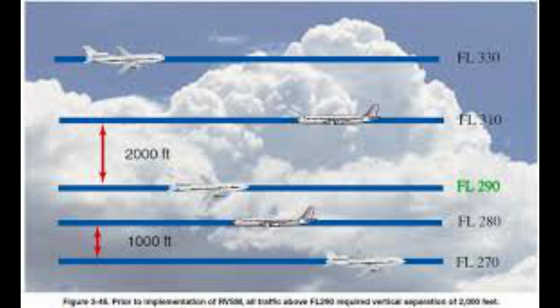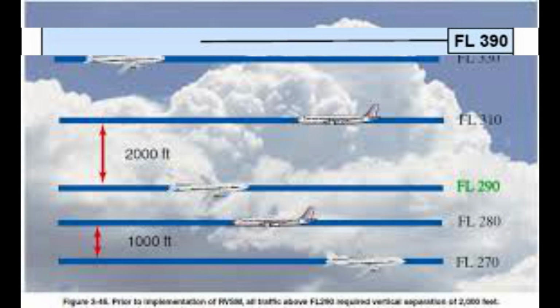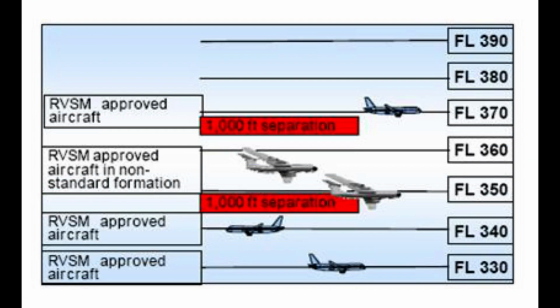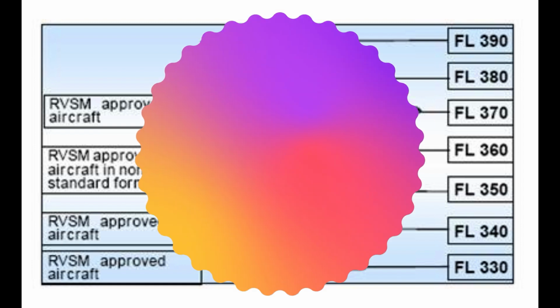The North Atlantic implemented initially in March 1997 at FL 330 through FL 370. The entire Western Hemisphere implemented RVSM FL 290 to FL 410 on January 20, 2005. Only aircraft with specially certified altimeters and autopilots may fly in RVSM airspace, otherwise the aircraft must fly lower or higher than the airspace or seek special exemption from the requirements. Additionally, aircraft operators, airlines or corporate operators must receive specific approval from the aircraft's state of registry in order to conduct operations in RVSM airspace.